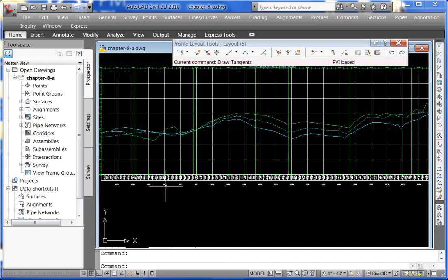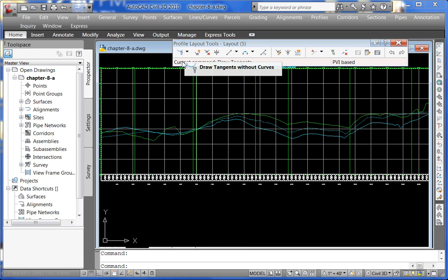Okay, now that you're back from page 242, we're just at exercise 8-3. I'm sorry, my apologies. So you have this window open here, and the first thing we want to do is set the radiuses or the parameters for the parabolic curve. So we go to this first icon, go all the way to the bottom, and go to curve settings.